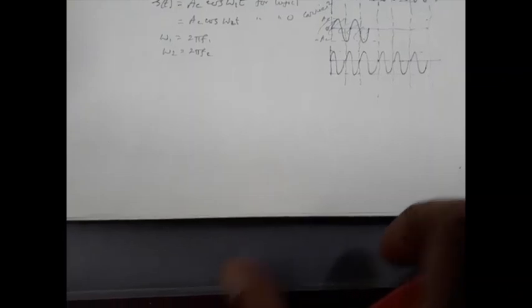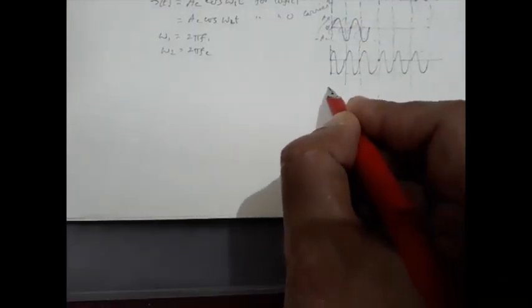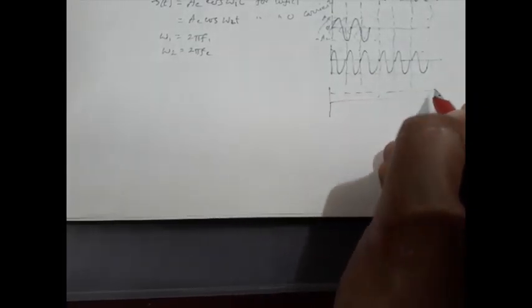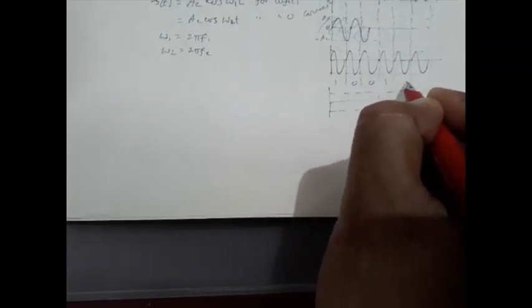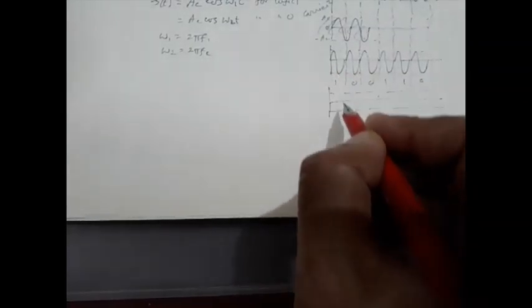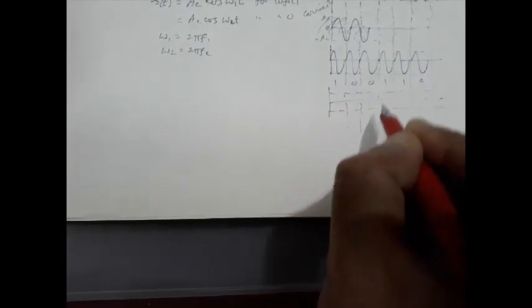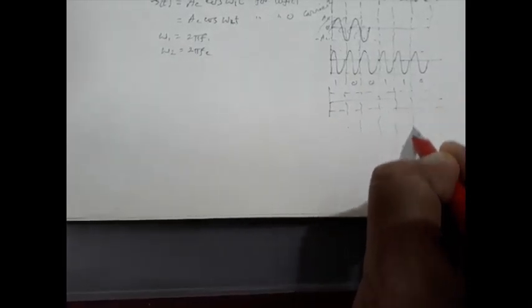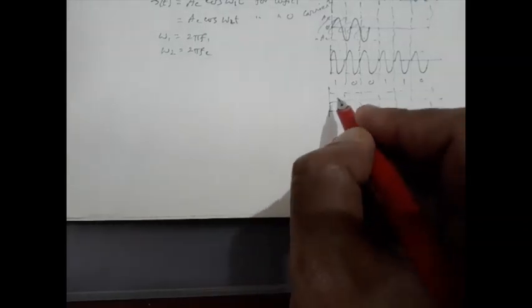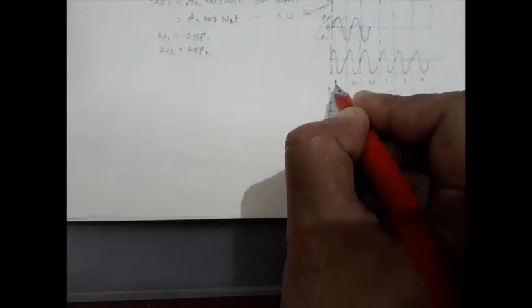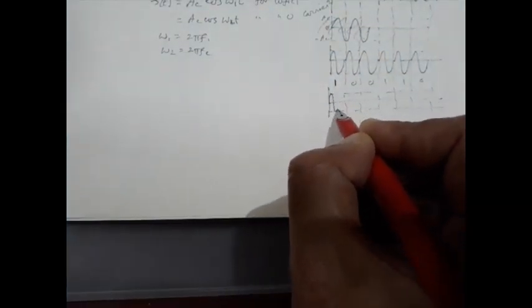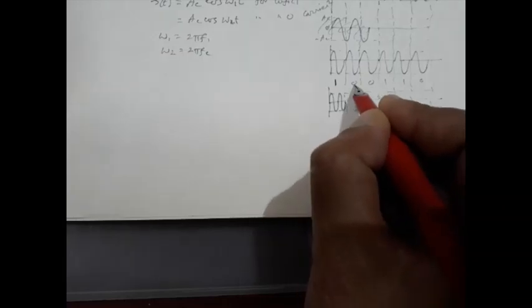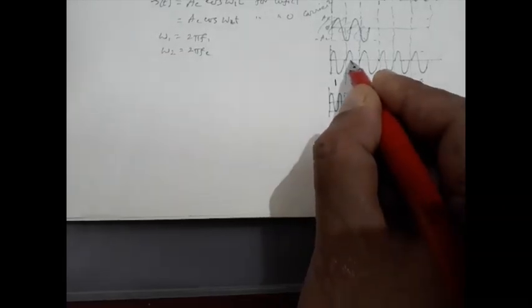So if we have a given data, that data may be anything like 1 0 0 1 1 0, say. So the waveform of FSK signal will be like this. Logic 1 will be represented by this carrier. So within this bit period we have 2 cycles. Now we have logic 0, means this carrier.